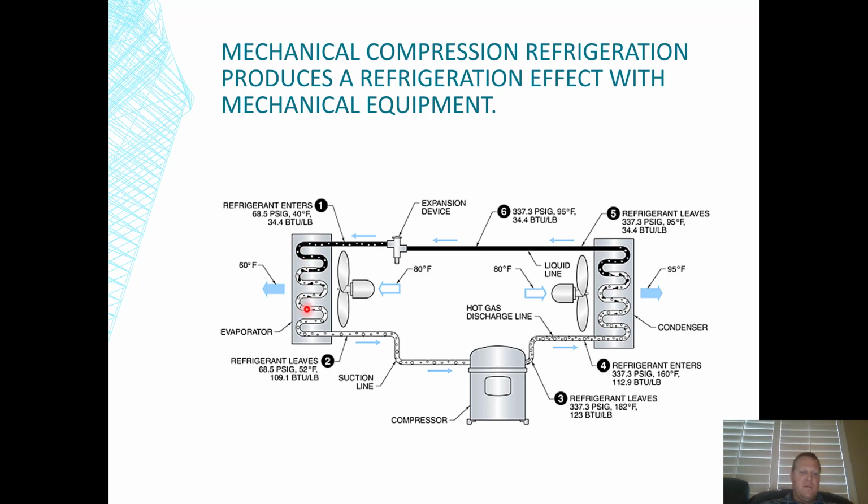And what if, rather than trying to cool air, we just cooled some more water and sent the water off to somewhere that was really cold, like a coil inside of an air handler? So imagine this being cooling water, not cooling air, pulling the heat out of the water as it makes its phase change from a liquid refrigerant to a gas refrigerant, and from high pressure to low pressure. So imagine it still getting all its heat, not from the air, but from water.